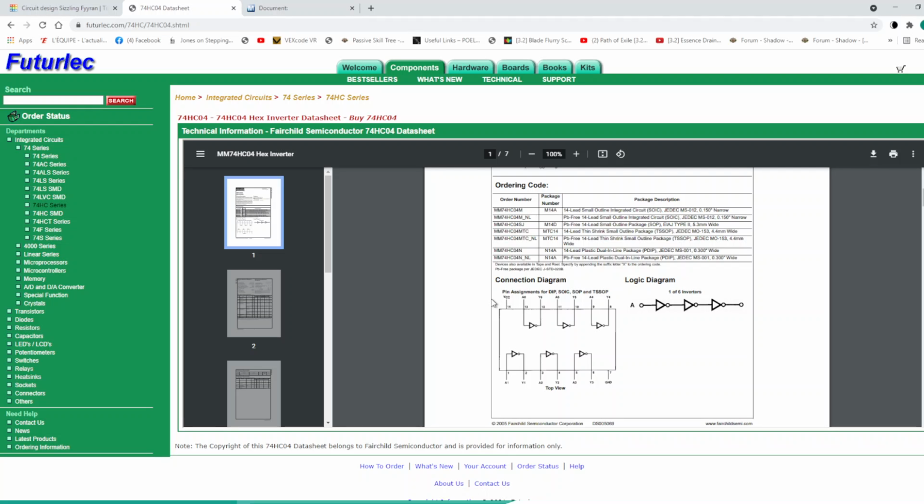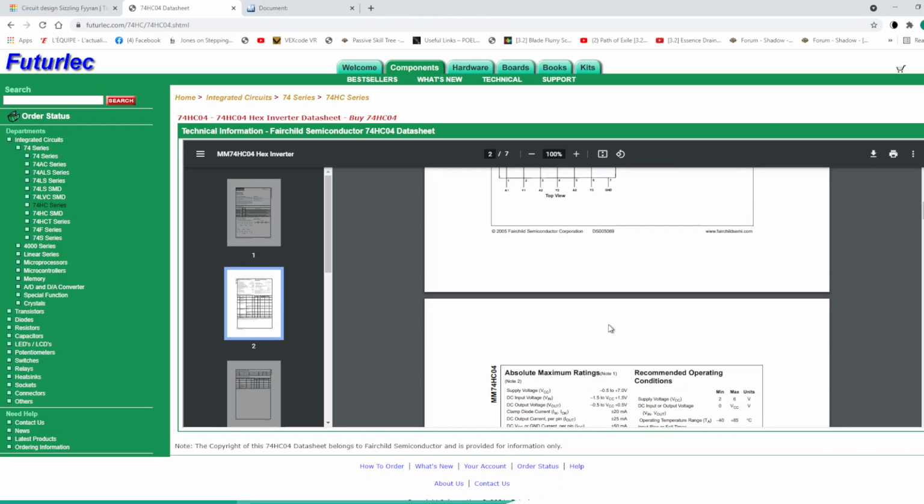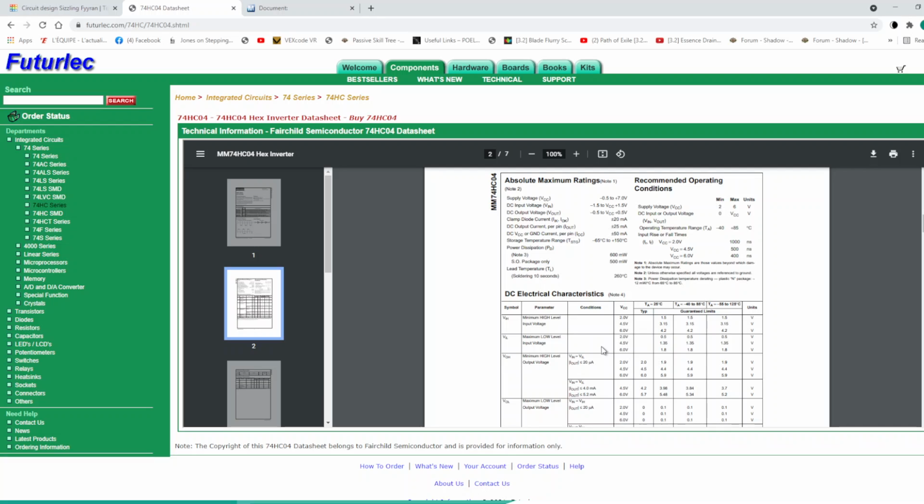Now, I'm saying 5 volts because that's what I'm used to when I deal with TTL. Okay, transistor to transistor logic. But if you look at this data sheet right here, this is not TTL logic. This is CMOS. Okay, you see this thing right here, CMOS. It says CMOS technology right here, and so it has the same functionality as the 74LS logic family, but the voltage levels are slightly different. Okay, so if I look below to the second page right here, you see that the supply voltage, VCC, is going to be okay between 0 volt and 7 volt.